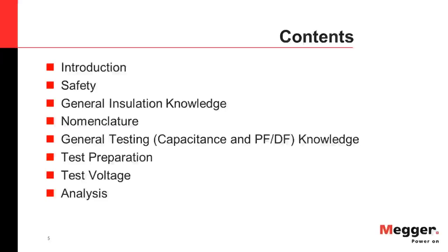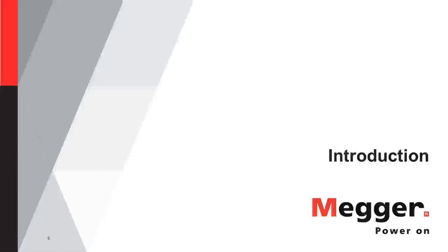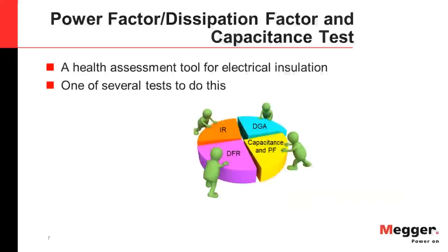So as I said, we'll anchor this discussion first with a few words about power factor and capacitance testing. This test is a health assessment tool for electrical insulation. I'd like to establish right away that this is just one of several tests to assess insulation. As the slide shows, insulation resistance, dissolved gas analysis, and dielectric frequency response tests provide additional measures of insulation performance and integrity. And each of these tests are necessary for different reasons, and together they provide a much more complete picture of an insulation's health and performance today, and in some cases may even uncover emerging issues.